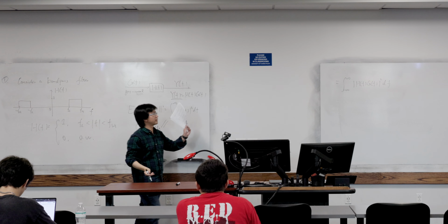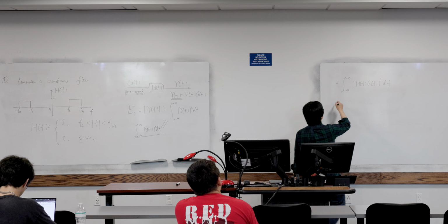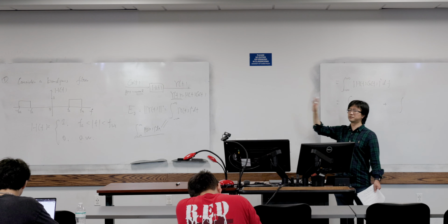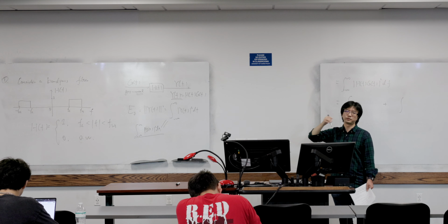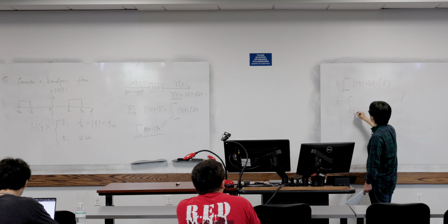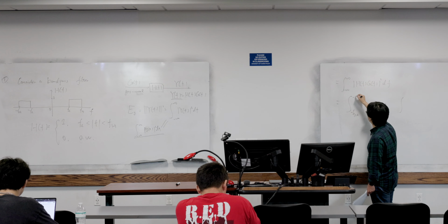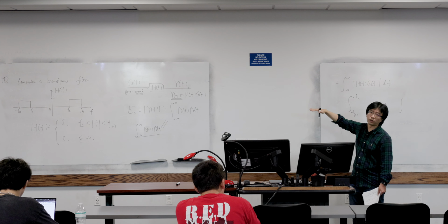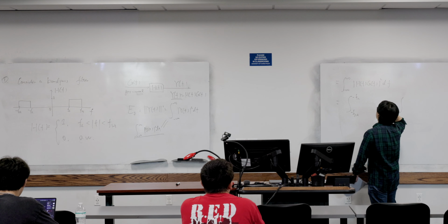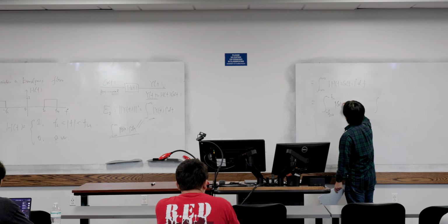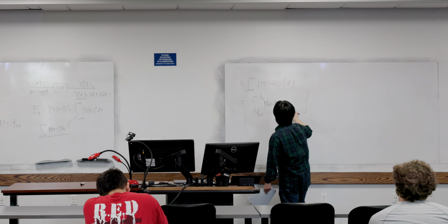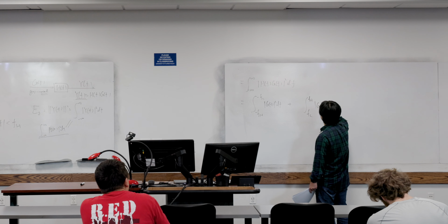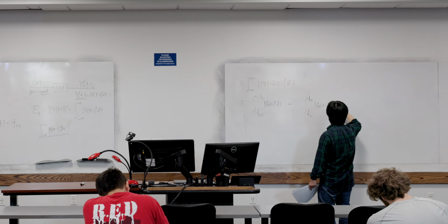So we can break this integral over two parts: one part is the negative frequency part, and the other is the positive frequency part. Basically, we integrate from minus fH to minus fL, where the magnitude of H is 1, so only |G(f)|² df is left, and on the other side, from fL to fH, this part is also left.